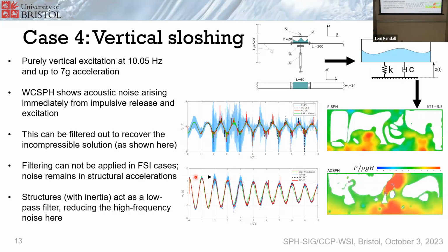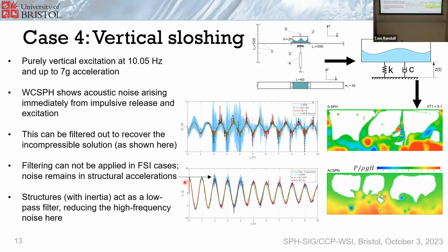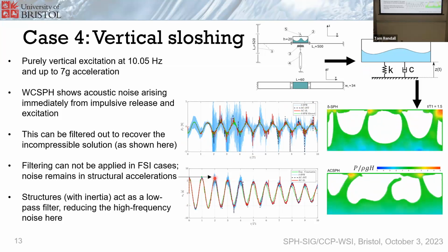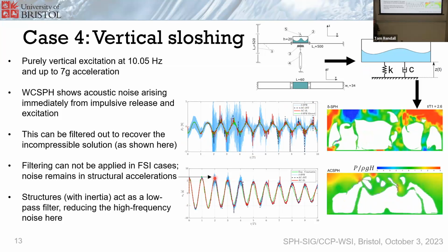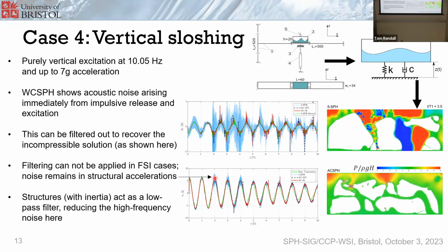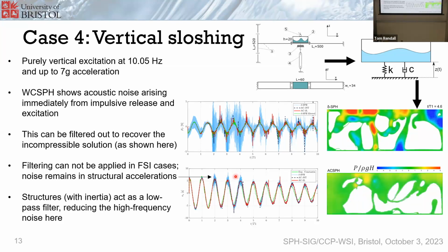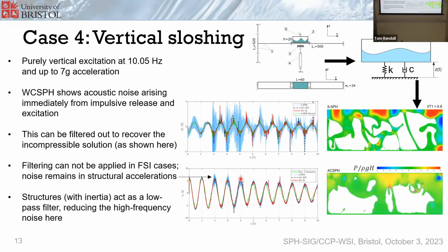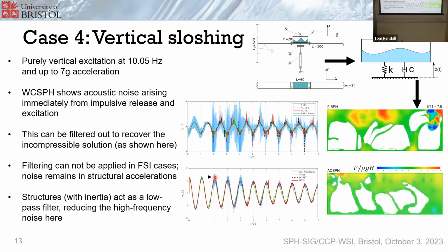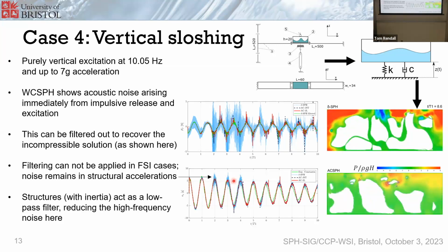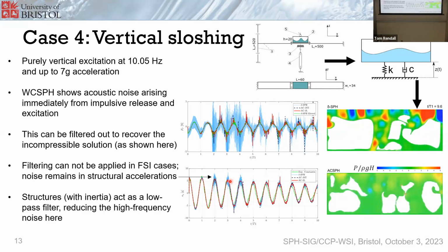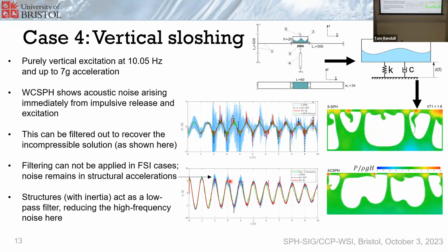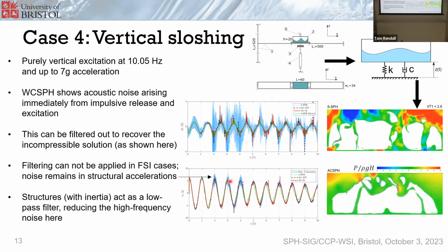And then the force is quite noisy, that carries through to the acceleration. So once you've integrated that, the inertial effects tend to filter out a lot of the noise in the response, but you still see noise in the acceleration, and it still comes through in the physical displacement results. So the improvement is going from the blue to the red. So we're reasonably satisfied that we've made an improvement in terms of those simulations.